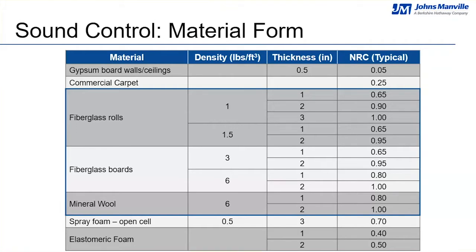Thin pile commercial carpets provide some sound absorption with an NRC of around 0.25. However, many facilities such as museums, hospitals, restaurants, or gymnasiums do not include carpet. They tend to utilize tile or even finished concrete. One thing we are seeing is that many open office plan spaces are moving away from carpeting as well. This further contributes to the overall noise level, as hard surfaces like tile promote reverberation rather than inhibit it.